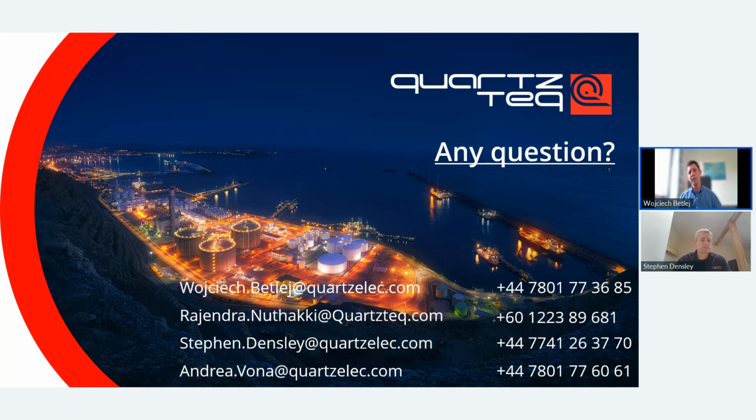You shouldn't be really worried about machines below 6 kV, because we know that for air-cooled machines, the trigger for PD to appear will be somewhere between 3 and 3.5 kV. But the higher the rated voltage of your unit, the bigger the problem you have. So if you operate an 11, or even 15, maybe 23 kV machine, look at PD, because it's happening.